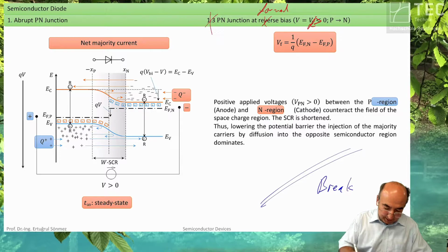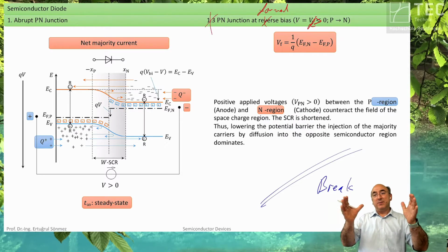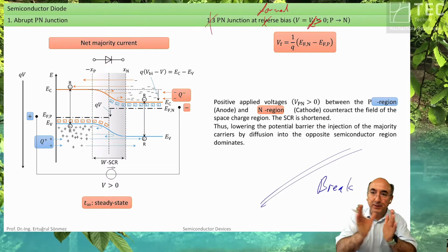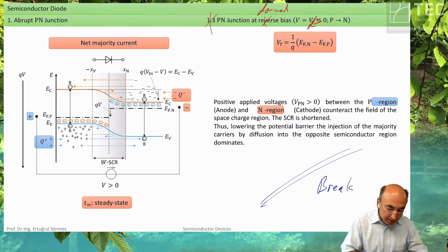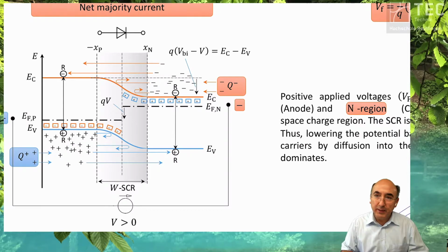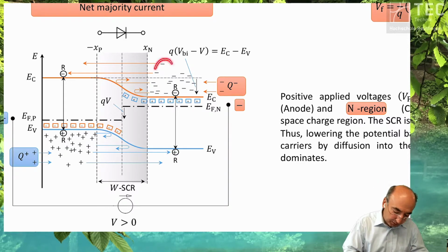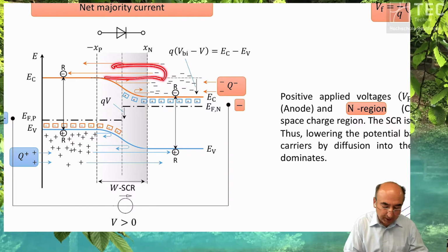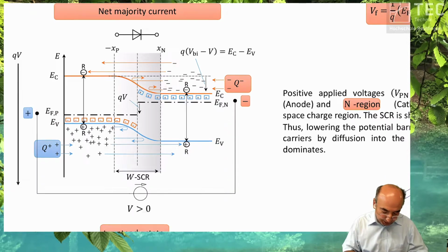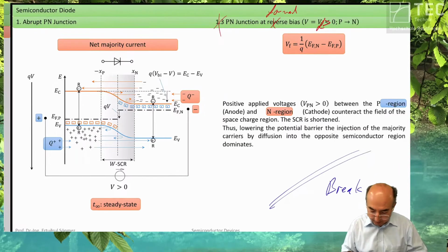We learned that forward biasing squeezes the space charge region. It counteracts the electrical field, thereby it reduces the barrier. And the Boltzmann statistics say that the amount of electrons which are above the barrier, which can diffuse over the space charge, increases exponentially, and therefore we now have an electrical current.